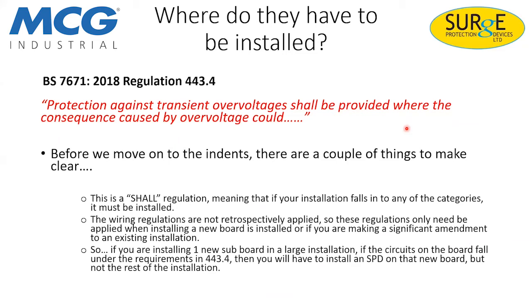The wiring regulations are not retrospectively applied. So these regulations only need to be applied when installing a new board or if you're making a significant amendment to an existing installation. So if you're installing one new subboard in a large installation, if the circuits on that board fall under the requirements in the indents I'm going to go on to in a moment, then you have to install the SPD on that board, but you don't have to install it on the rest of the installation. That is something you could recommend to your client, but it's not something you'd have to do.